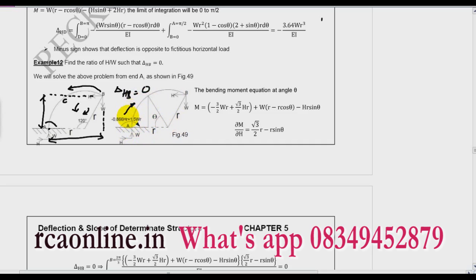Clear? So what you are doing, you are applying the bending moment from A to B, not B to A. So your limit will be moving like this. And what will be your limit? 0 here and 2 pi by 3, which is equal to 120 degrees. Now what is the bending moment equation? If you convert this, and then you write the bending moment equation, this is your fixed end moment, then the moment of W into lever arm.